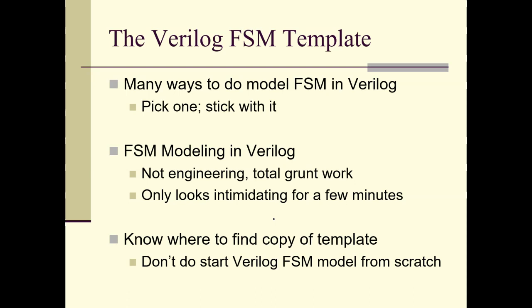Okay, once again, the engineering step is coming up with a state diagram. This is pretty much grunt work, translating that state diagram into a Verilog model. And I don't do this every time. I have a template out there, and it shows me everything I need to know, and what we're going to do is step through that template. Don't try to write this from scratch. You'll make mistakes. But you got to know the template. You got to know how the template works.